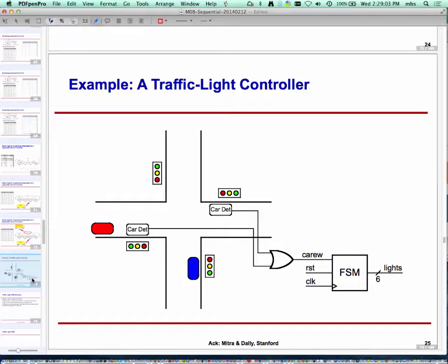And now you have to analyze it, and as I've often said in the past, instead of diving into gates and flip-flops, first think about the algorithm. The counterpart of algorithm when it comes to sequential systems is to first think about what my state diagram will look like. You have to first think of what the states are and how you are going to move between these states. Once you have done that, getting an implementation out of it is basically straightforward. You just follow some mechanical steps.